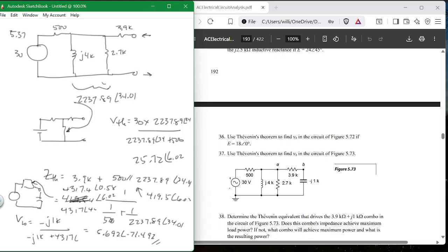It takes that imaginary part of your current and brings it down to zero, because you can begin to see that the minus J cancels the plus J. And that's what happens. So you bring the current down by putting some capacitance in it, and all of a sudden you bring it down close to zero. So you're having pure resistance to the best of your ability. And that's how you can maximize the power that is used in your plant. That makes sense?